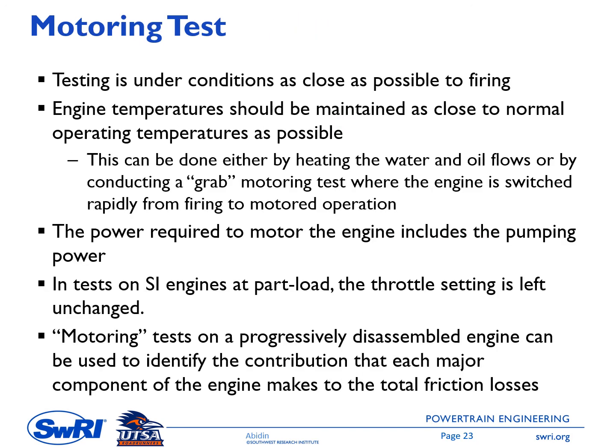For motoring testing, the test is under conditions as close as possible to firing. This means the engine temperature should be maintained as close as possible to the normal operating temperature. Either we can heat the water and oil flow, or conduct what's called a grab motoring test, where the engine is switched rapidly from firing to motored operation. The power required to motor the engine includes the pumping power.